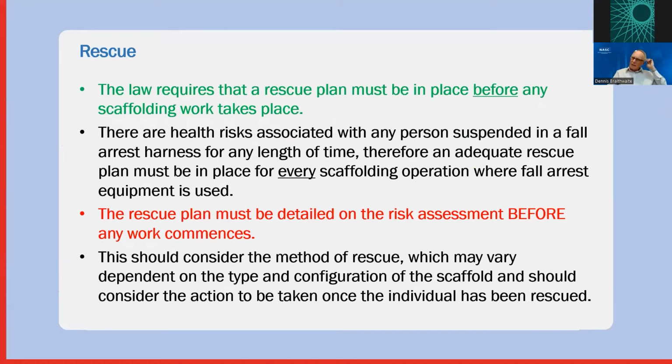The law requires that when working at height, we must have a rescue plan. I'm sure you understand that there are health risks associated with anybody that is suspended in a harness when they've fallen for any length of time. So therefore, an adequate plan must be in place for every scaffolding operation where fall arrest equipment is used. And this plan must be detailed and on or certainly with the risk assessment, and it should be available before we start work.